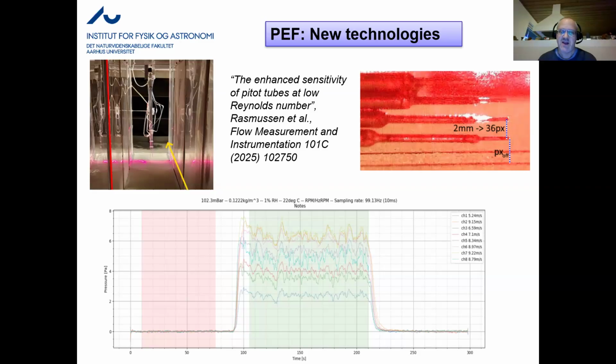Another one is that at low pressure, you go into the essentially Stokes drag regime for these pitot tubes, and they function essentially independent of pressure. So you get a great enhancement in signal compared to if they were larger scale ones and their Reynolds number was large.